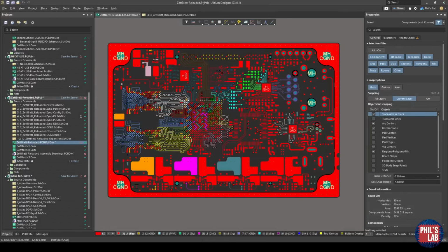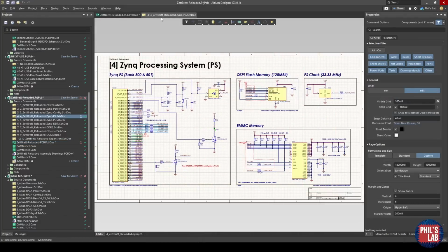Once you're happy with your manufacturer information, you've generated the Gerber files and any additional information that can help your manufacturer out, it's of course time to generate assembly information, assuming you want your board assembled, that is. What I encourage you to do, even in the schematic stage or when you're creating your component libraries and footprints, is to include information on the part.